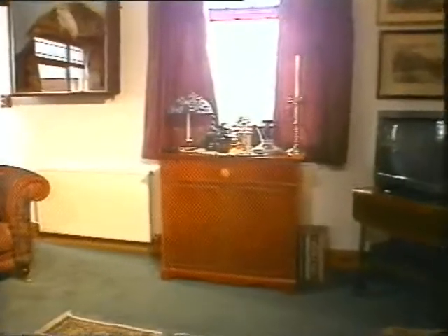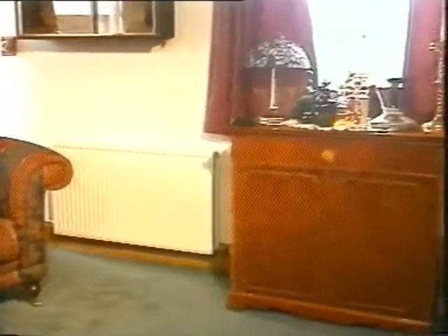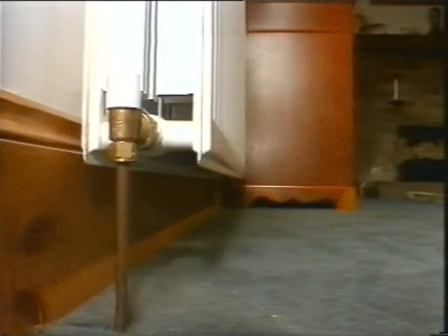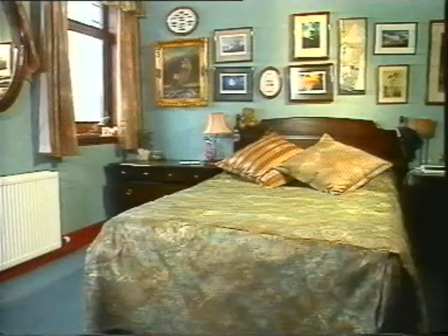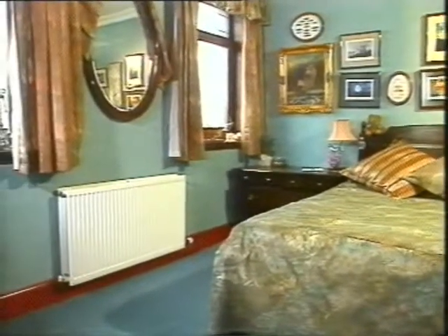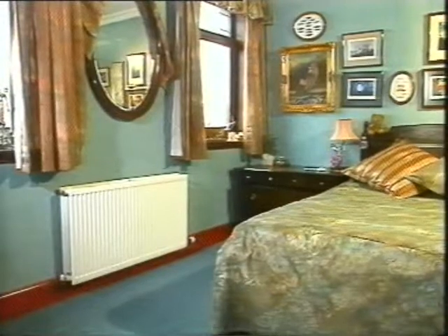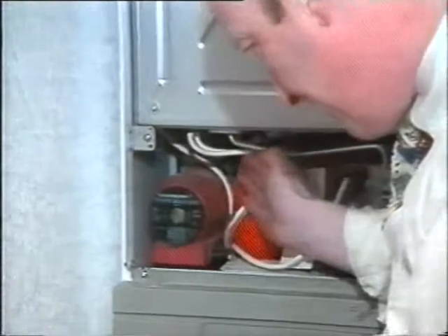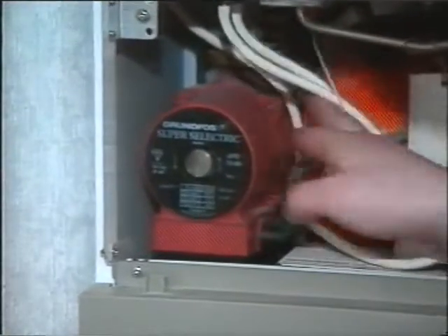Microbore's easy to install, but it may not be suitable everywhere. In hard water areas there could be scaling, and if the pipe's diameter is reduced to the radiator it's serving, the radiator won't reach its designed output. So the choice of pipe is important and depends on lots of factors. Your manual has guidelines on how to calculate your needs. There are more calculations to make before choosing the correct pump for the circuit.